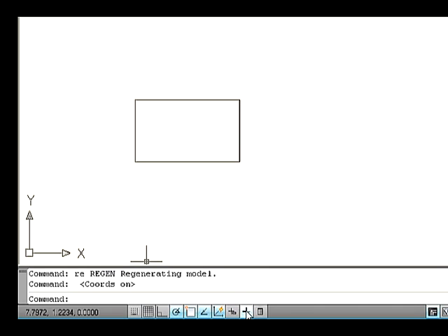Show and hide line weight, LWT mode button. One of the properties that you can assign to objects in AutoCAD is line weight. The line width appears when plotting the drawing. This button controls when you see the line weights on the screen. Quick Properties. The Quick Properties panel displays the commonly used properties for each object type, thus making them easier to find and improving access to them. With the Quick Properties panel, you can edit properties for a selected object or for all objects in a selection. This is a new button included in AutoCAD 2009.